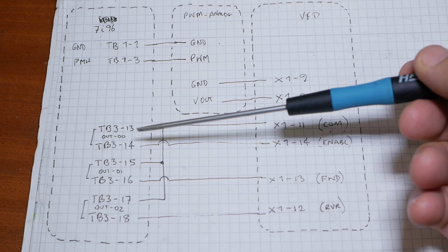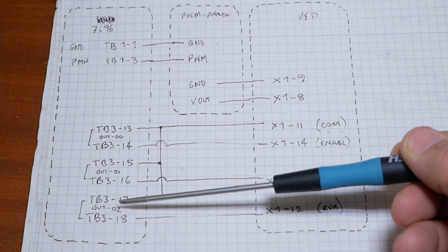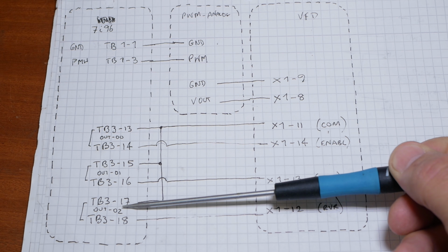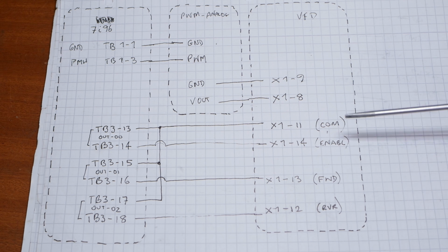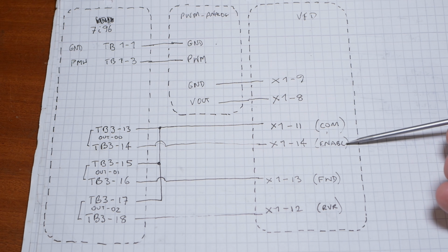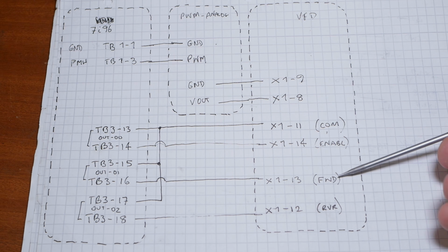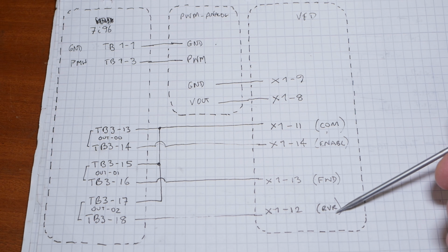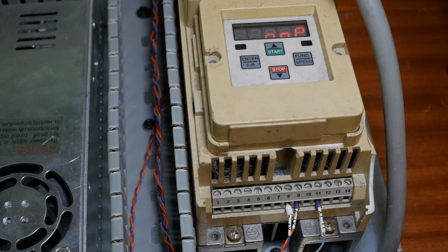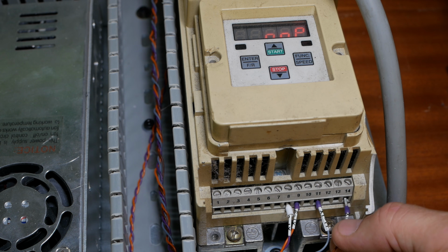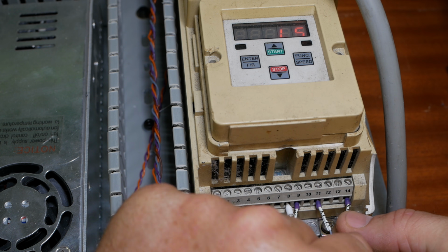Now I've connected 3 of the output switches from the Mesa card to control the VFD's enable signal, and then its forward and reverse switches. Unfortunately, I've got this problem. As soon as I connect a signal, it immediately goes active.